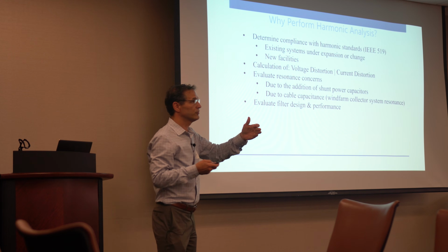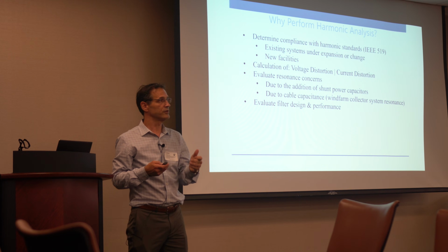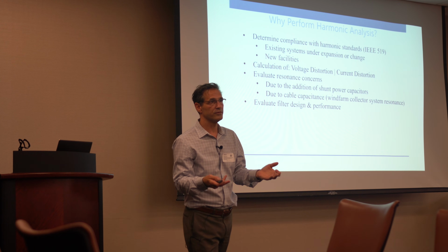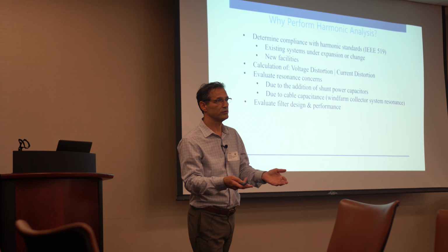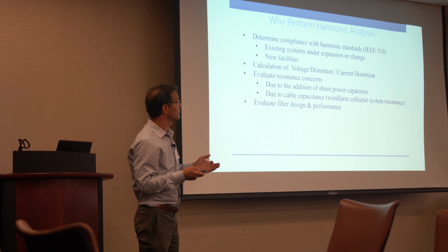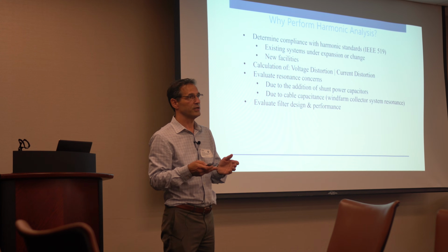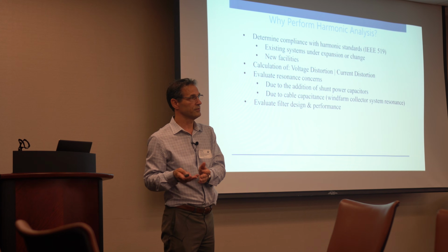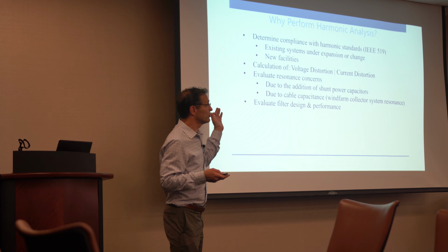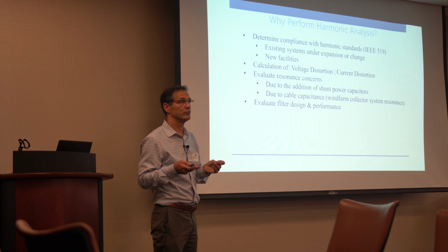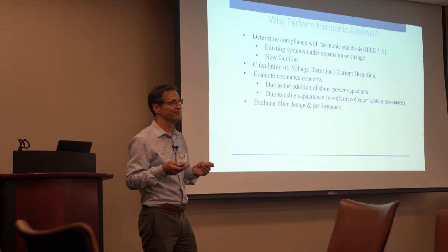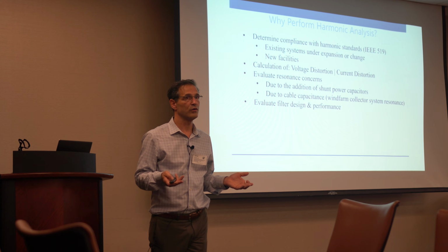Within the plant, you're concerned about voltage distortion. Right? You're installing a large drive in the plant, and you're concerned about voltage distortion. It's very important to calculate voltage distortion throughout a plant because it's voltage that impacts all the other equipment in the plant. So that is not concerned about current distortion within the plant environment because the current's just flowing in the conductor. It's not causing anything.